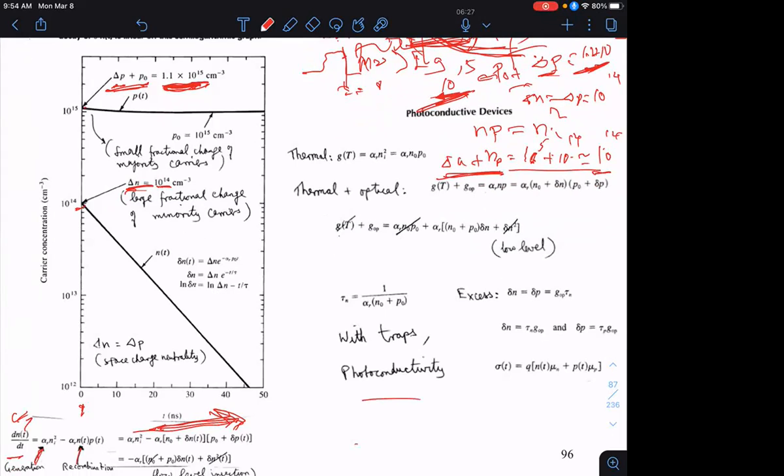Now, if I have many electrons and holes that I've created, delta n and p naught plus delta p, versus a scenario where I have only a few electrons that I've created, in which case do you think this recombination process would be more rapid?